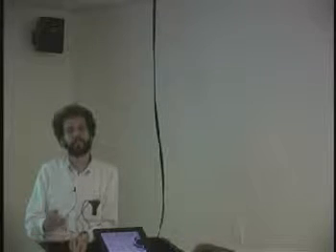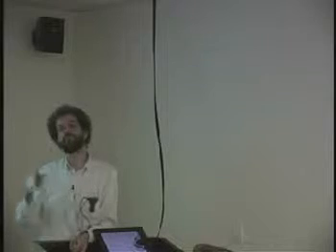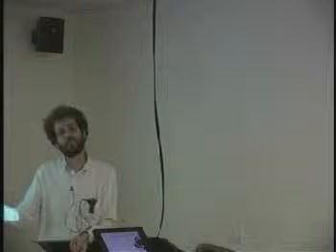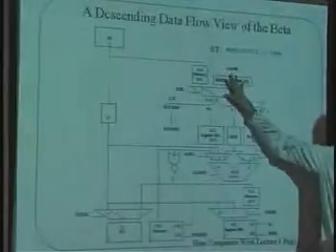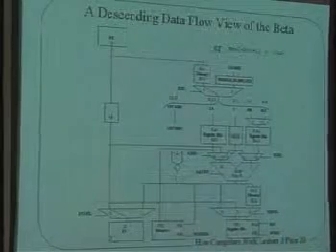What we do instead is we have an idea of an interrupt, which means that when a key is pressed, whatever code is running at the time is stopped. We jump to a handler to handle the person pressing the key. When we're done handling the key, we jump back to where we left off. And so it's a forced subroutine call that we didn't expect. We didn't know when it was going to take place. I'm not going to talk about the detail of how that works, but know that the mechanism here is for handling those types of things. Okay.